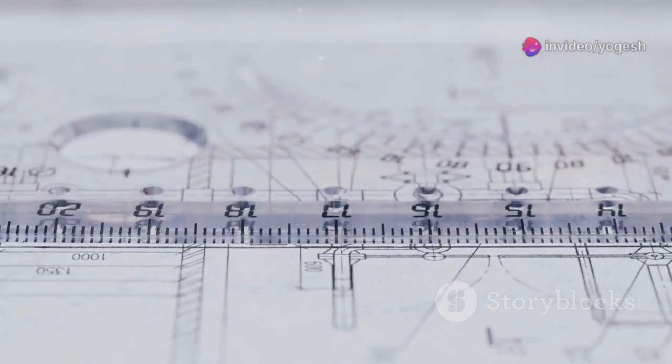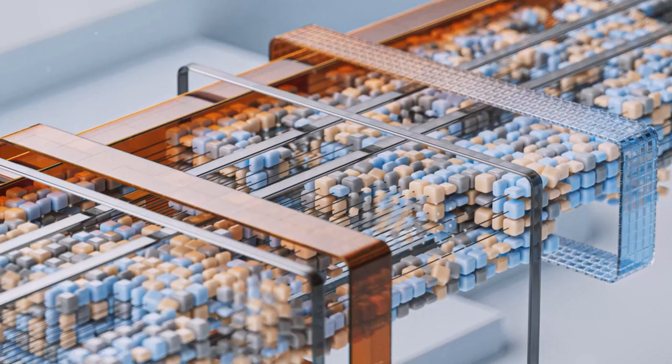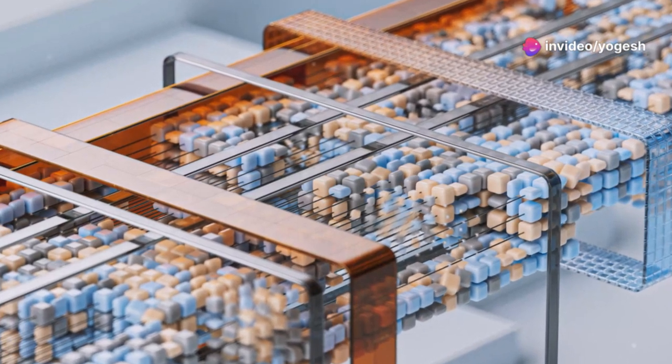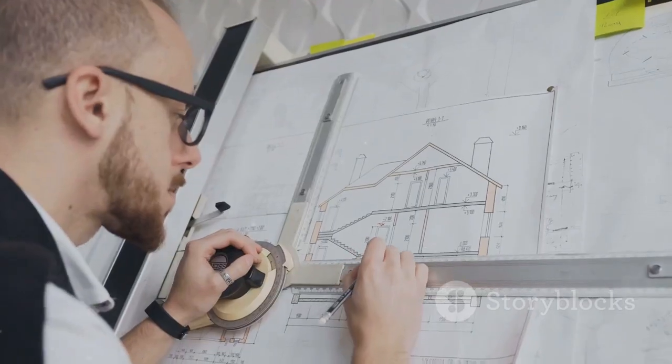The cutting plane line is a thick phantom line with arrows. Label it clearly, like AA, to link the cut and view. For simple parts, labels might be omitted. Clarity is the goal. Follow these rules for effective communication. Sectional views should be clear and unambiguous. They are a visual code for builders.